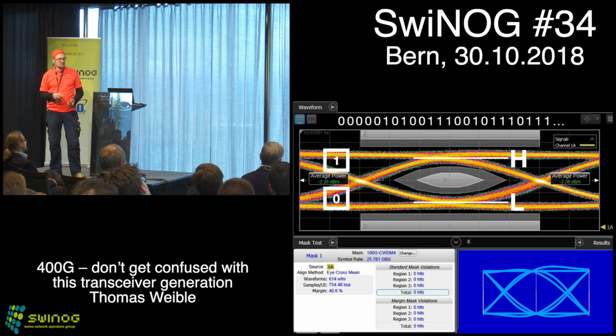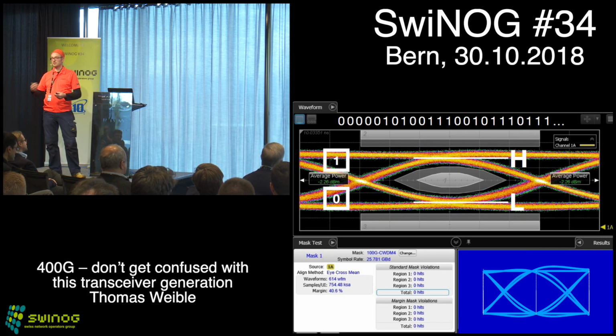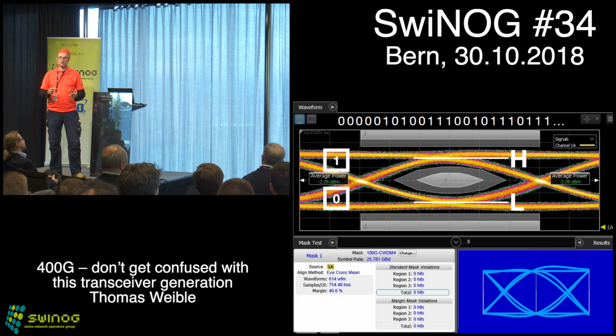So that's what gives us the possibility that our transmitter goes through those different states, but it should avoid going through that area, because on the other side of a transmitter there is a receiver, and that receiver needs to detect whether it's a low or high event. And if, for example, our signal were corrupted and went through that area, the receiver wouldn't be capable of identifying, hey, was this a high or low event? And that's really an important thing of an eye diagram. So you need that shape, and you need to make clear that the transmitter is able to transmit properly on a high or low level. And that's what you want to avoid.